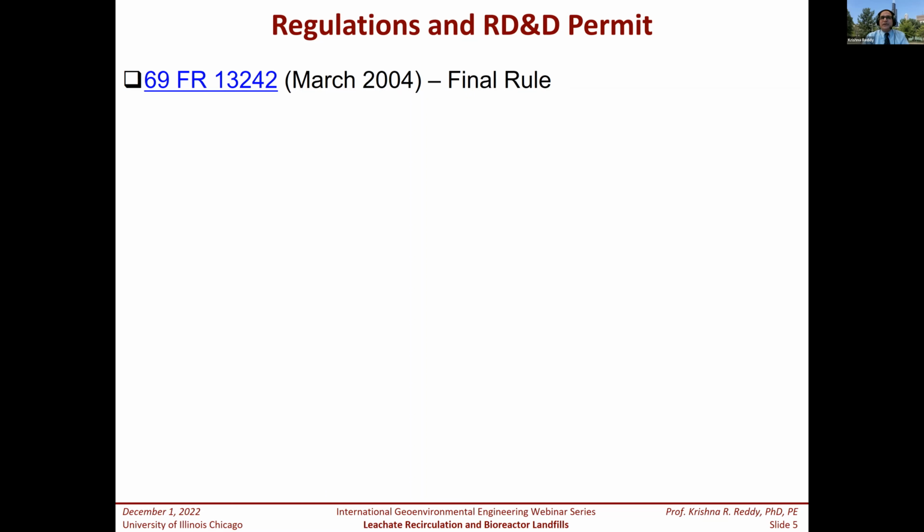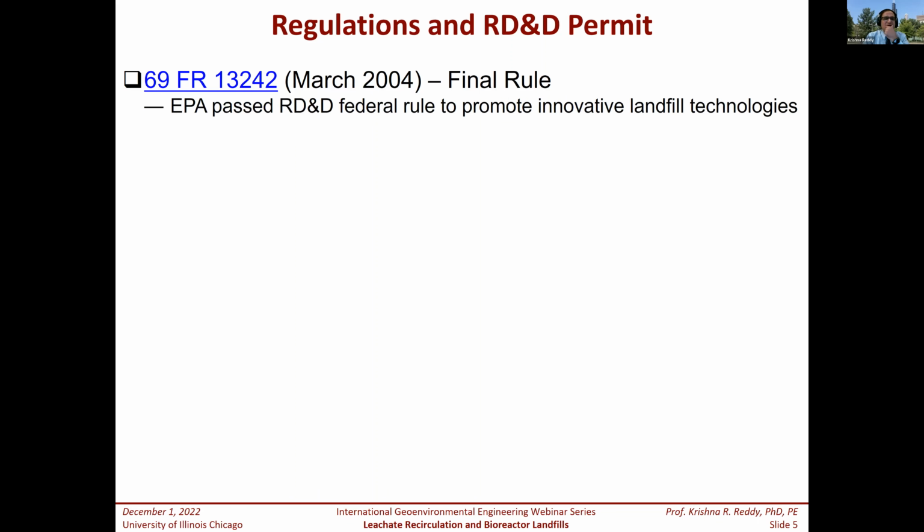It's very important to control that leachate at the bottom of the landfill. Otherwise, you're going to create a lot of subsurface contamination that will lead to a lot of issues. So in the US, this bioreactor landfill concept is considered to be very good, but there's a lot of caution in terms of how we can use it.